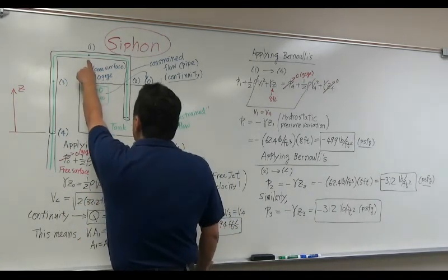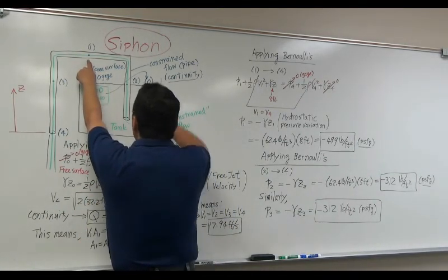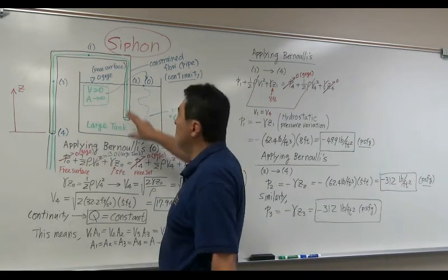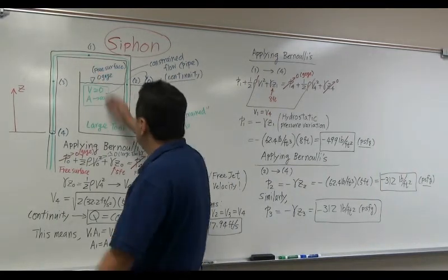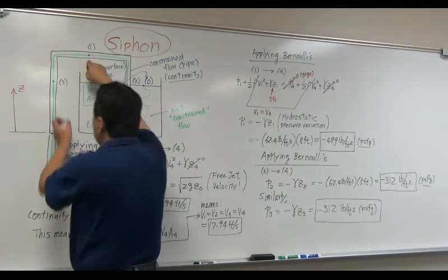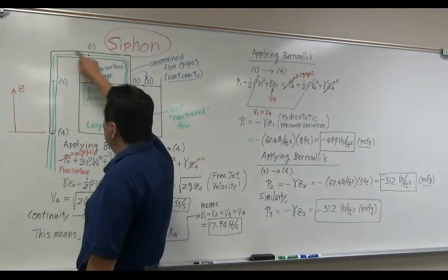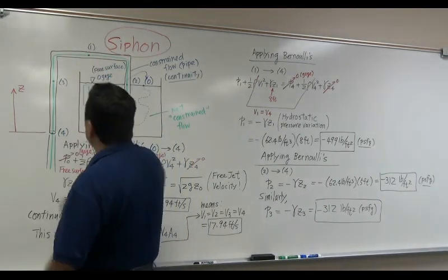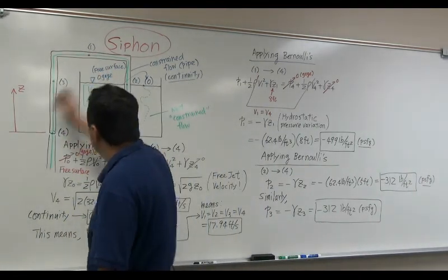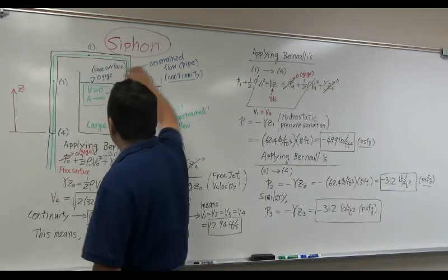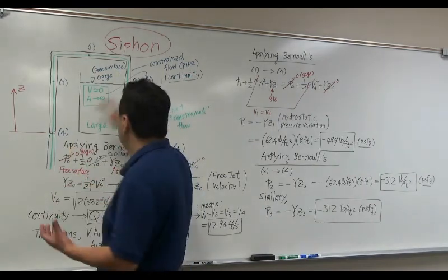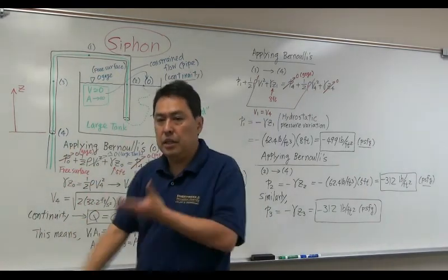So this is the low pressure point, this is a zero gauge. So between those 2 points, because of the pressure difference, low pressure sucks the water up to this point. Okay. Then from here to there, this is a low pressure, this is high pressure, but because of the gravity, water drops off. So this is a gravitational acceleration driven flow. From here to there is a pressure difference driven flow. So once you establish that, it is going to keep going without needing a pump.